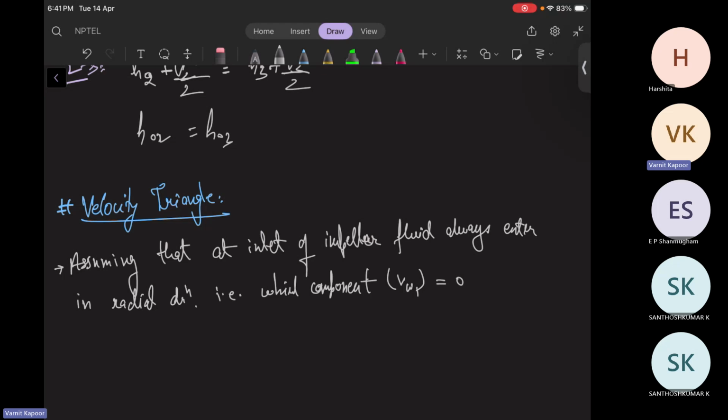So we have to come to a midway of both of them, neither forward nor backward. So we came across radial curved blades because they produce a balance, and they are preferred because when you have a centrifugal effect, it creates bending moments and develops high stresses that may damage the blade profile. So radial blades are always preferred. And if nothing is mentioned in the question by the examiner about what kind of blade is given, then you always have to assume it is a radial blade.